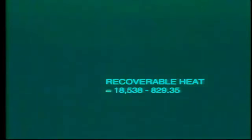The real implication of this is that all of the heat in the hydrogen contained in the fuel is in fact not available. In other words, the recoverable heat content of the fuel oil is actually 18,538 minus 829.35, and this equals 17,708.65 BTU per pound.